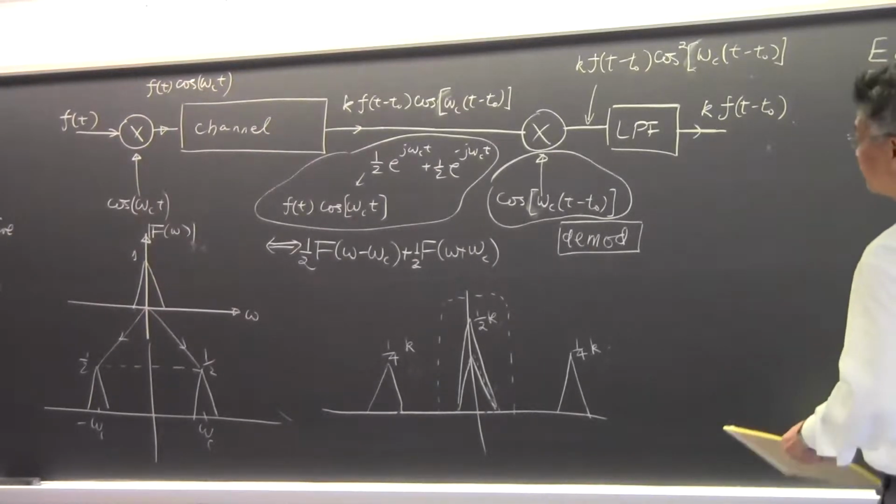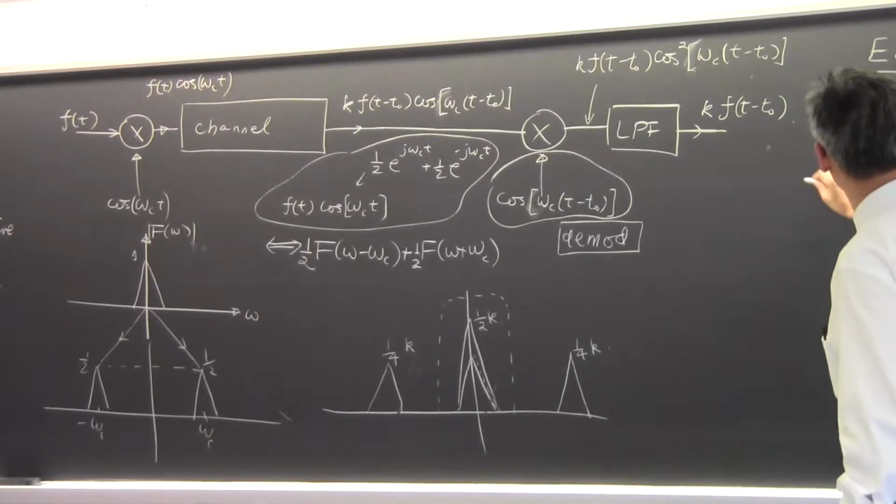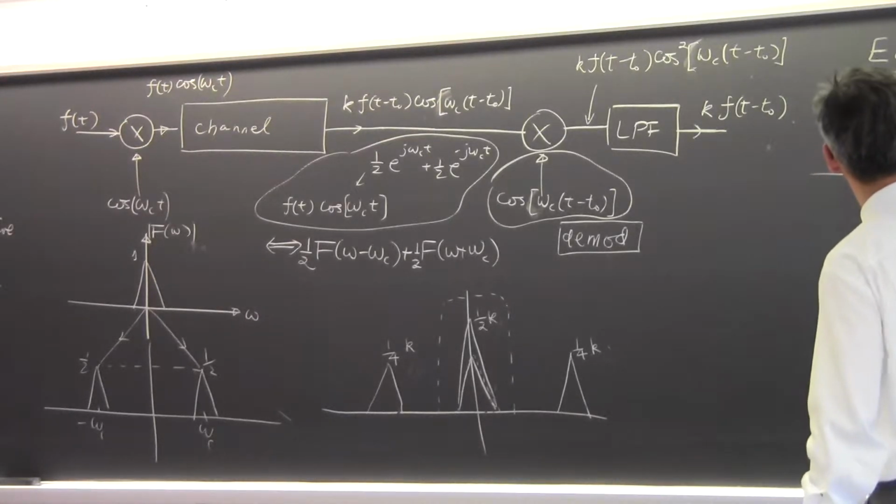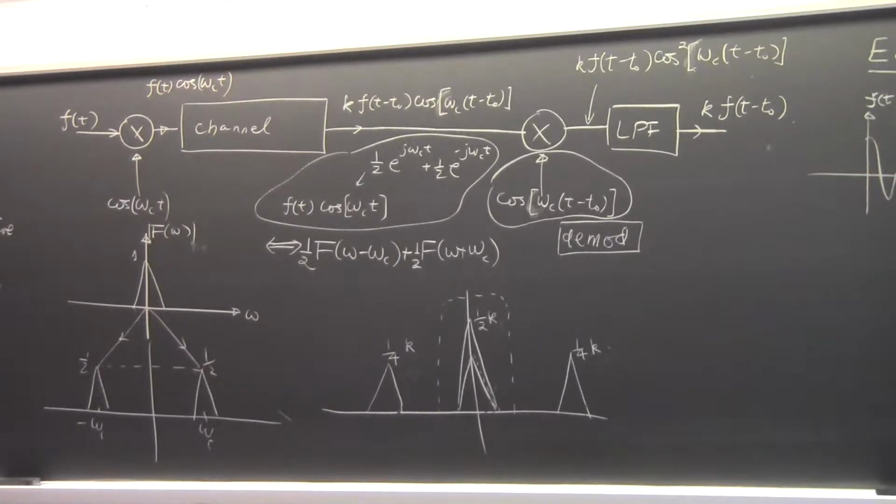So what you do is a trick. If I have any signal f of t, I know that if I modulate this signal with a cosine, it becomes a big mess. So instead of directly modulating this signal with a cosine carrier, I shift it upward so that it never becomes negative. I add a DC term to it so that this is f of t plus alpha.